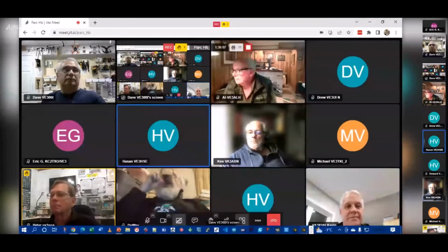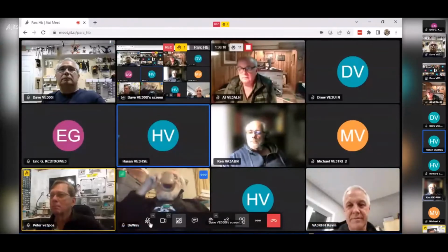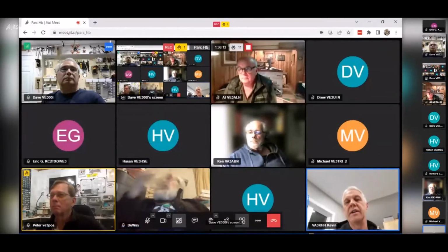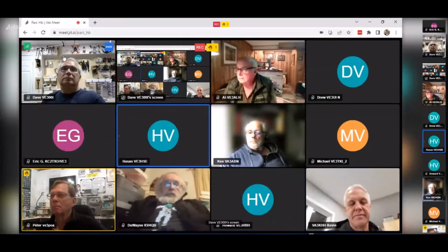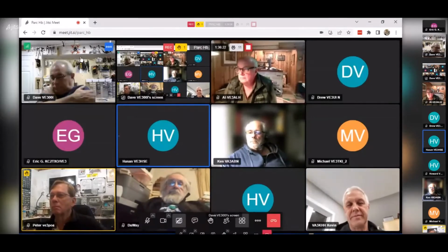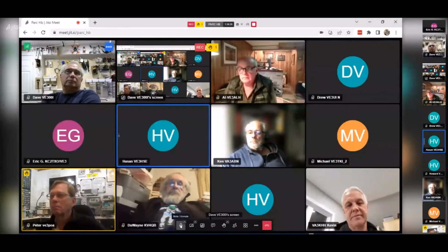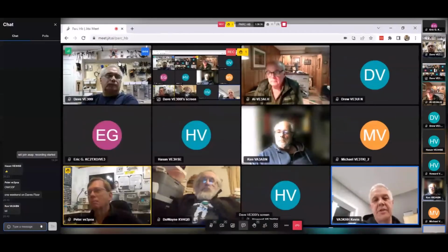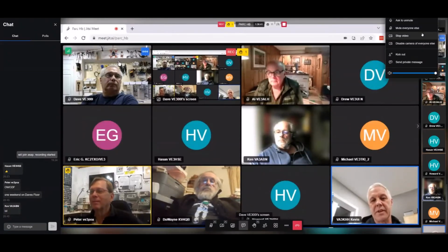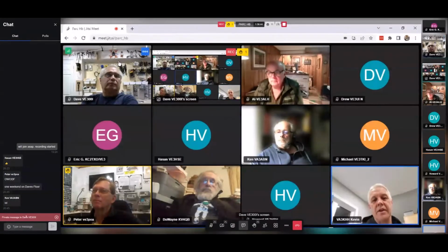On that note, Kevin, so a servo motor always has a controller built in. Is that correct? Well, or yeah, you need a controller for it. Yes, a servo motor. Yes. All right, so that simplifies everything else because now you only have to tell it the angle to move to, and or speed. I guess a servo positioner, you give it the angle, and a servo motor, you give it the speed. Well, it depends how many loops you have, right? If you're regulating position, you're going to have a position loop that drives a velocity loop, and the velocity loop drives the torque loop, and the torque loop determines what the motor really does. Ah, interesting. So if you don't want to control position, then you get rid of the position loop. You just tell it how fast you want to go. And if you don't care how fast you go, then you just say how much torque you want.